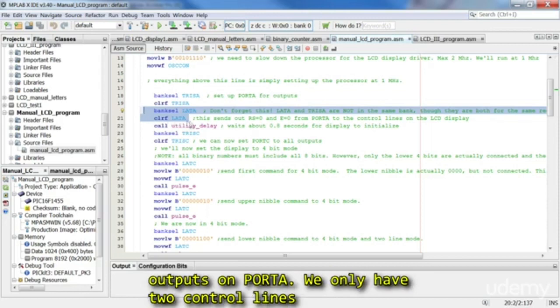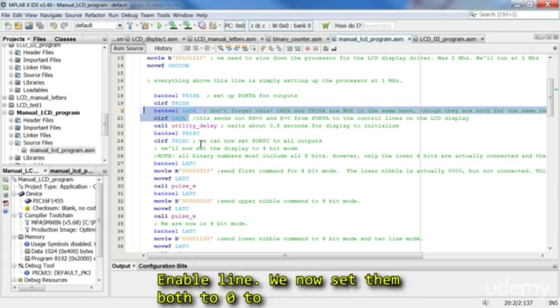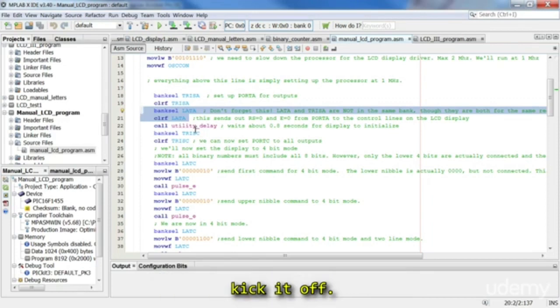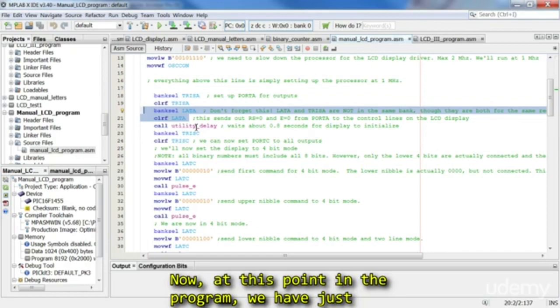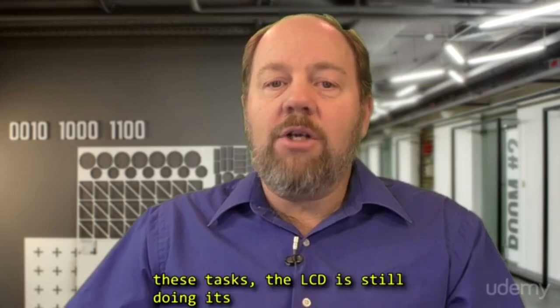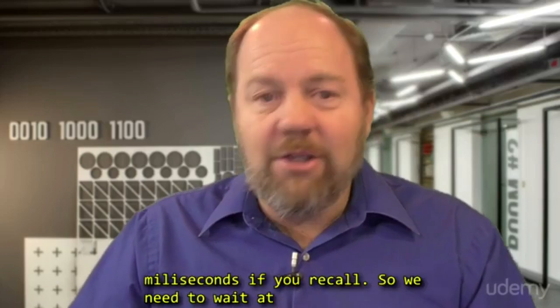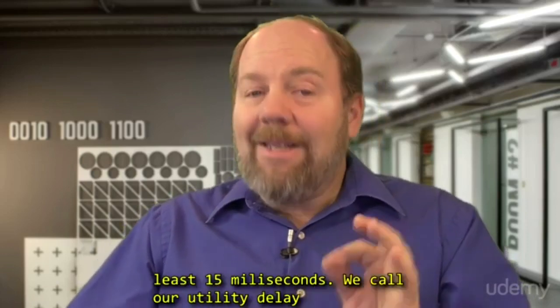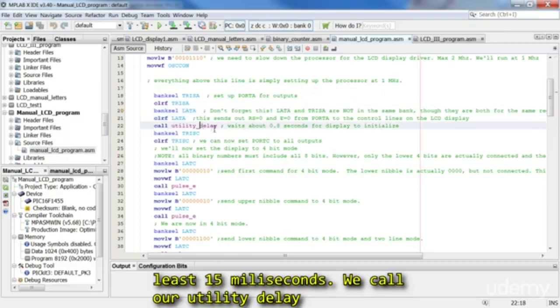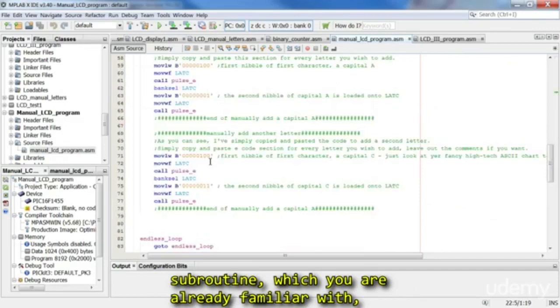We clear all the outputs on port A. We only have 2 control lines wired into port A, the register select line and the enable line. We now set them both to 0 to kick it off. Now, at this point in the program, we have just powered up. So while the PIC has completed all of these tasks, the LCD is still doing its initialization, which takes forever, 15 milliseconds if you recall. So we need to wait at least 15 milliseconds. We call our utility delay subroutine, which you are already familiar with way down here.